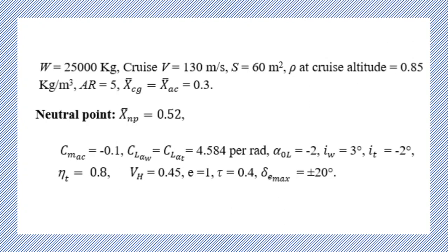Stable. Why? Because your XNP minus XCG is a positive quantity. So your static margin is positive.